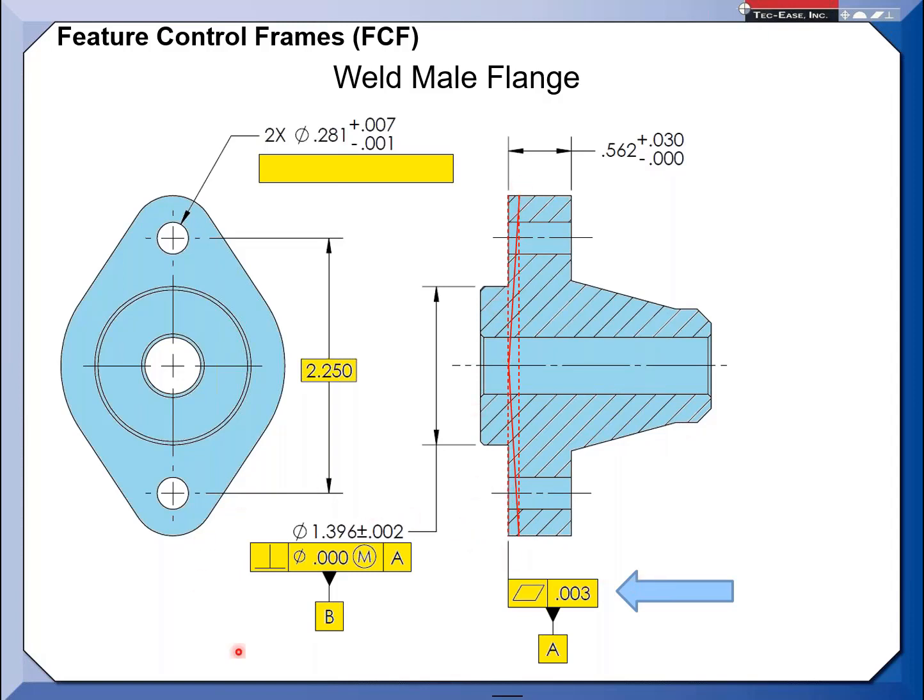Now, engineering is where they're going to have to decide what these values are. In this design, I did leave off a component. There is a gasket that really fits between these 2 flanges when they come together, and that gasket would absorb the difference of what the surface variation could be. So believe it or not, there was another material, but I didn't want to make this problem so complicated. The reason I'm speaking to this is I've gotten some feedback from people that are engaged and did the challenge.